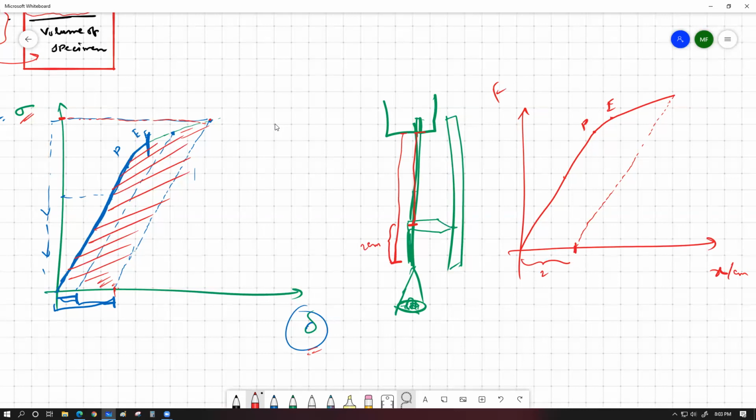The way we talk about the energy amount is actually the area under the graph. So one of the things that I need to understand, whenever we are applying the loads over here piece by piece, the object is becoming longer. So we are applying more force, the object is becoming longer. So it is undergoing deformation. In this process, elastic energy is getting stored within the specimen.